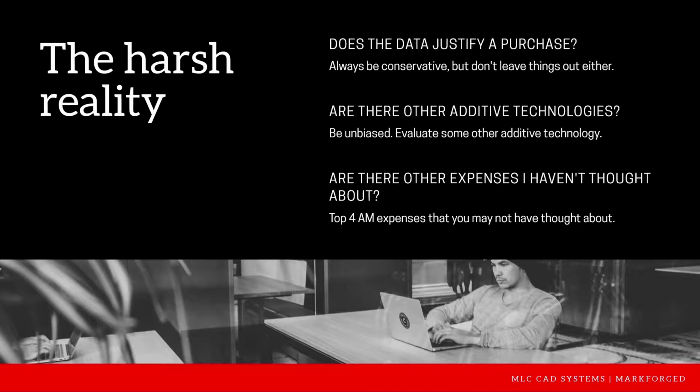It's not even bad practice to add an additional 10 or 15% to your materials cost or your operating cost, because there are some occasional variables that come in. One thing, we like to test parts sometimes. If you've got a really geometrically complex feature and you're not sure how it's going to work out on the larger part, you can break that off the larger part and print just that piece. If it's a success, you move forward with the rest of the part. If it's a failure, then you scrap that idea to print that. And so, occasionally you'll have a second iteration here and there depending. So add some cushion for yourself.